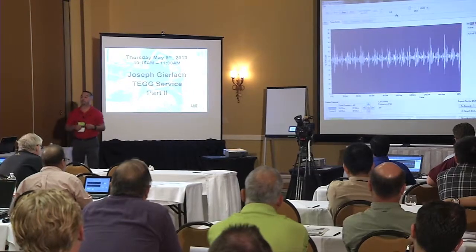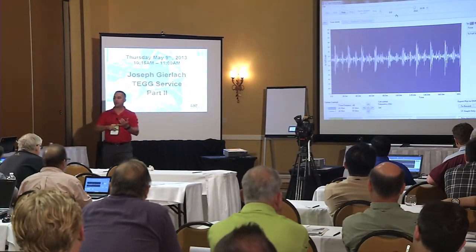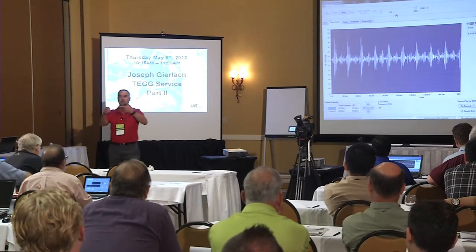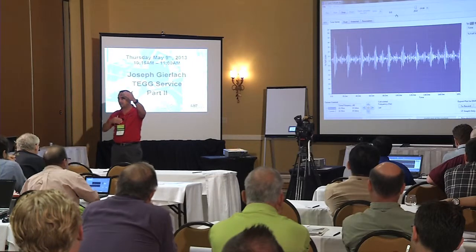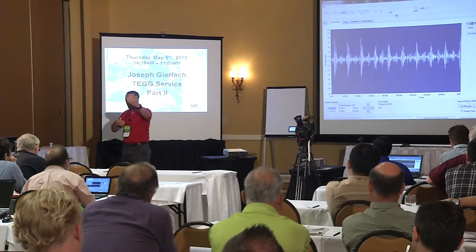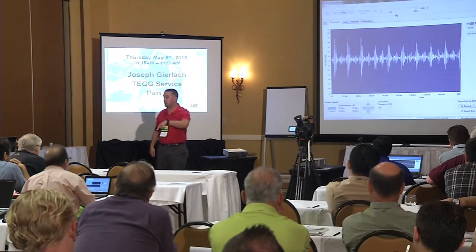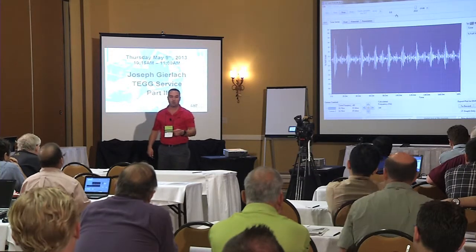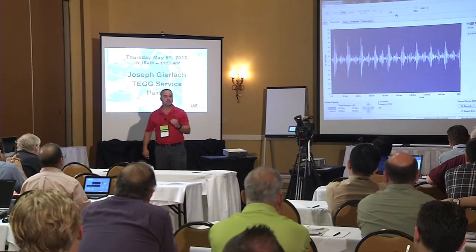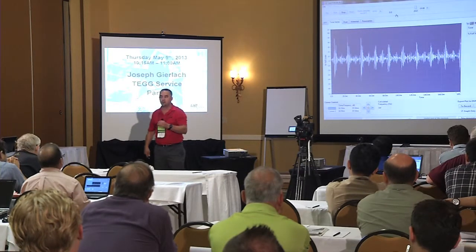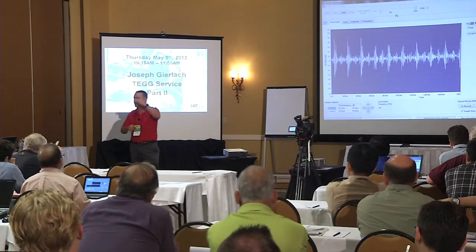That could be a number of different things, in my opinion. If it was a contact probe, does pressure on the probe have anything to do with the intensity we might see? One of the things I learned real early on is if you're going to do trending, you'd better have the same pressure on the measurement point if you're using the contact. That could play a role. Fluctuations in the load level will change it too. We just looked at the file, so I don't know for sure, but those are some things I've seen that can change the amplitude.